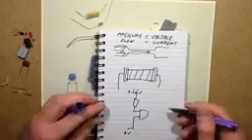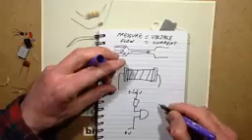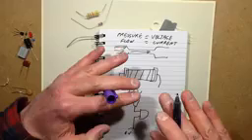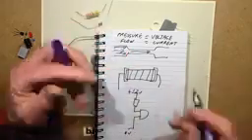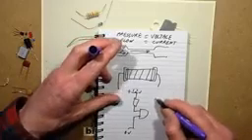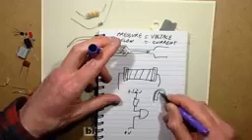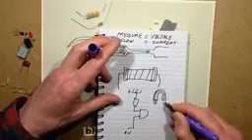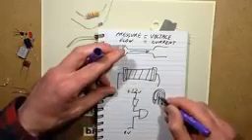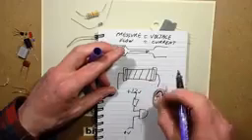They're also used for things like time delays. You might have a resistor charging up a capacitor, it trickles the current into it until the voltage reaches a certain level, and then that could be used as a timing function. And you also get variable resistors where effectively it's a carbon track connected at both ends. You only really need to connect at one end, and with a wiper that actually wipes round that track, so that depending on its position, that will vary the resistance.